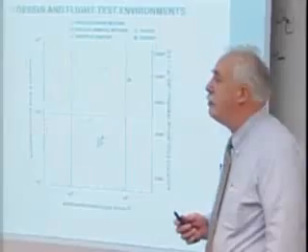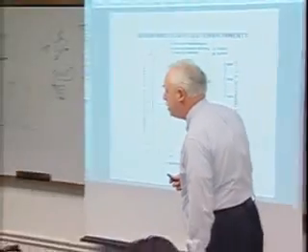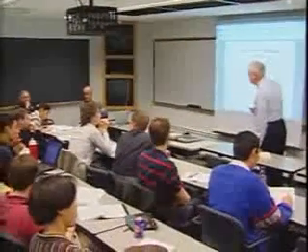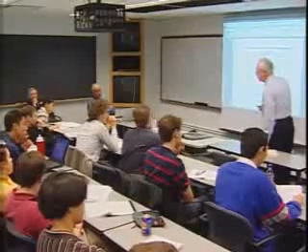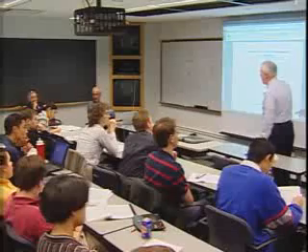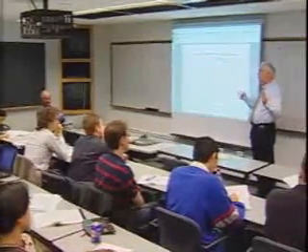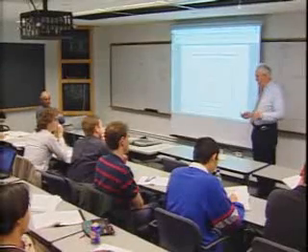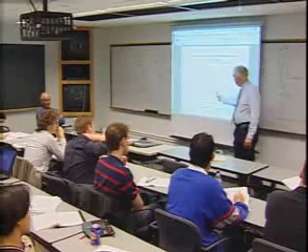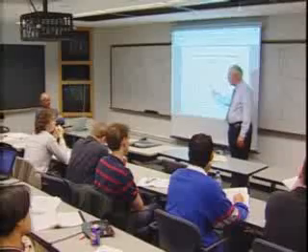Okay, any questions? Yes. So how much does your ability to control the trajectory play into that? It seems like you'd be able to control the trajectory of the shuttle a lot more precisely than you would in Apollo. Yes, absolutely. Got a body flap on there in particular to trim angle of attack. We also have RCS engines, which we'd use if we have to, and in some cases we have to. And you've got aileron settings, which primarily are used later. But yes, crucial. In terms of getting this level of precision, you need control.